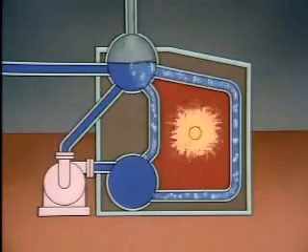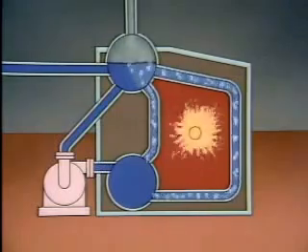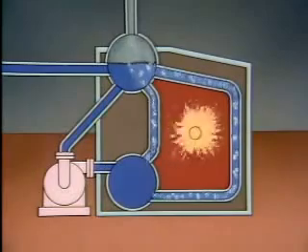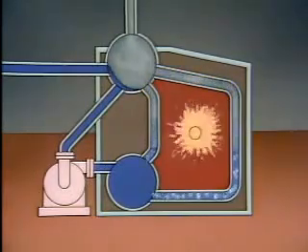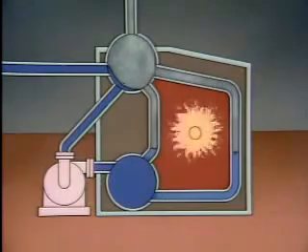If the pump circulates the water through the drums and the tubes, the boiler will operate as it's supposed to. Hypothetically, though, if the pump stops, the water will no longer circulate properly, and the boiler could boil dry and become damaged. To make sure there is proper water flow, most controlled circulation boilers use 2 or more pumps. So, even if one pump stops, the other pump will provide enough circulation to prevent damage to the tubes.